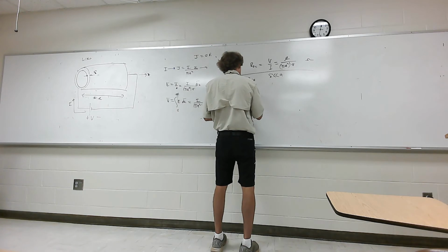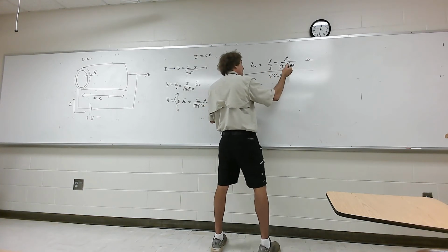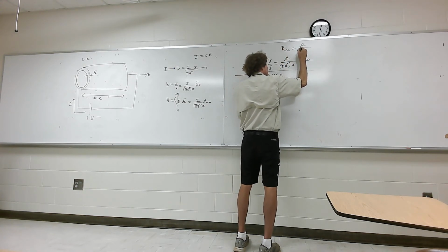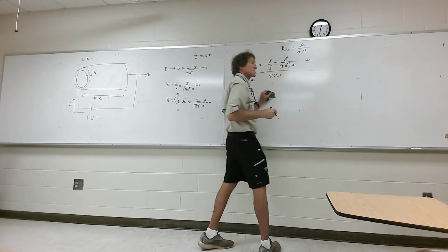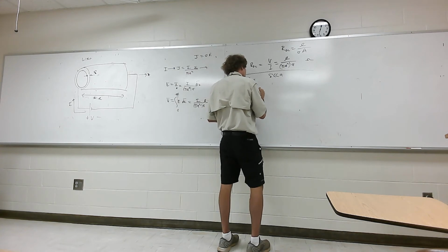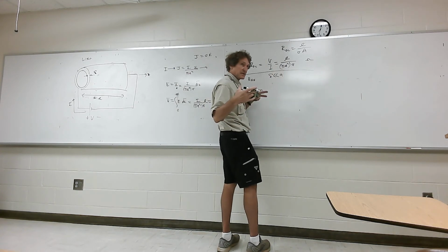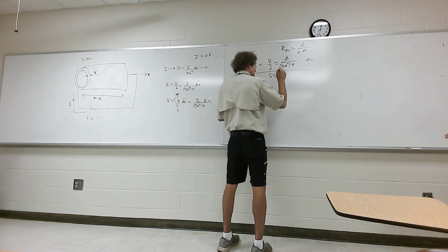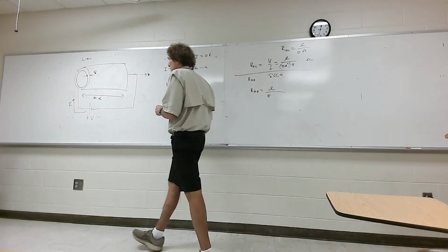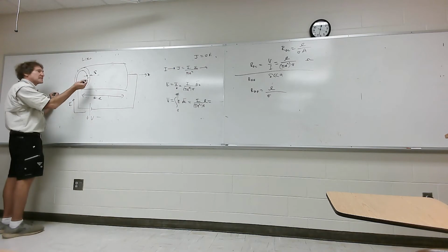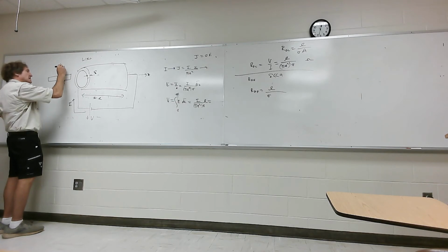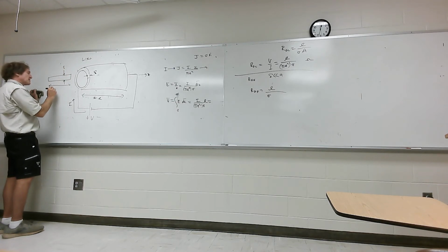To get this resistance, remember what we found up here for the DC resistance: it's proportional to length, inversely proportional to sigma, and inversely proportional to the cross-sectional area. Y'all follow me? Now when we get the high frequency resistance, the only thing that changes is the cross-sectional area. It still has the same length, and sigma is for the material used, copper, whatever. I think I told you how to do this, right? You just break that thing and lay it out flat. It's a skin depth thick, and the length of it is the perimeter, 2 pi a.